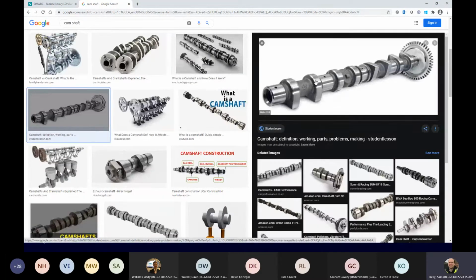As part of the processing of the camshaft, we need to measure the lobe displacement with the angle. So perhaps for every degree, we want to take a measurement of the lobe distance. We'd have a sensor on each of these lobes to measure the displacement, and we'd have an encoder to measure the rotational angle.